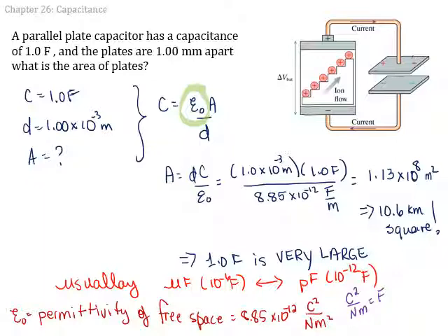In this capacitance example, we have 2 plates just separated by air. If we put something between the plates, we wouldn't use epsilon naught anymore because the electric field is not going through air, it's going through the stuff. Then instead of epsilon naught, we would use epsilon, which talks about how electric field goes through stuff. And the stuff we put between the plates is called a dielectric.